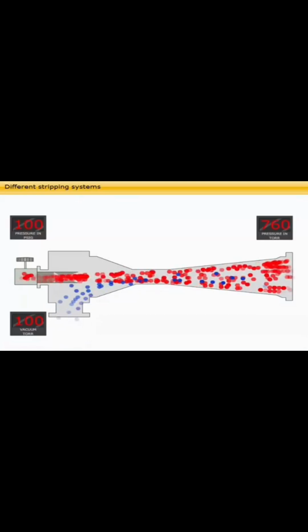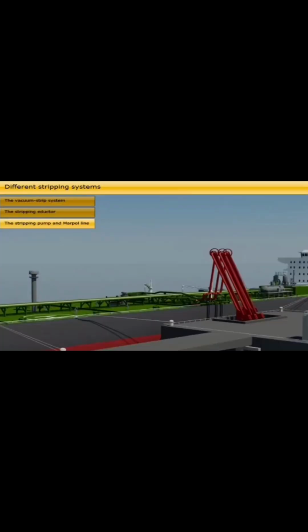Another reason is that it creates a vacuum continuously for fluid as well as gas directly in the cargo tank, if the tank becomes dry temporarily and gas pockets form in the suction pipe. A stripping pump would stop and start, and a vac strip pump would need a good quantity of oil in the pipe. When the crude oil washing is completed, the after crude oil washing checklist is to be completed.